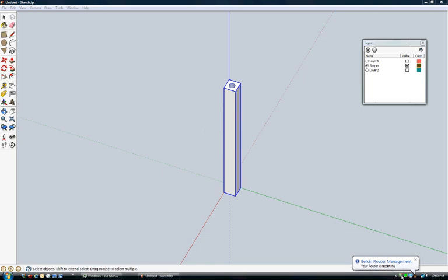So I'm going to go up to the top here, and I'm going to go on the face. Now I could draw other lines on here to reference this. I'm not going to. I'm going to click and select. Now again, I can set a specific radius on this one. I'm going to make this 3/4 of an inch. That'll give me 1.5 inches. Let's even back that off because this is my radius. Let's make that 1/2 inch, so 0.5. Now that's drawn the circle on that face.